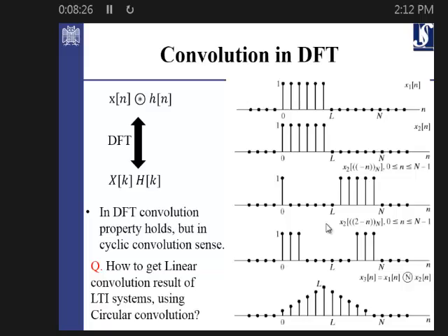actually perform the same. For example, if you have the time signals convolved circularly, which is a circle, and the sign of the convolution in the middle. In the DFT domain, the result is multiplication. And you remember from the linear convolution, it was the same for the continuous time signals. So we had x(t) and h(t) as a filter. Again, we had a linear convolution, not the circular one, but the result in the Fourier domain was exactly the same. It was a multiplication of the filter with the signal. But the way that they are convolved is quite different.